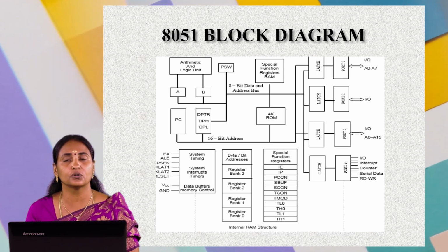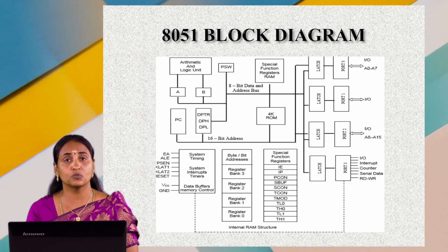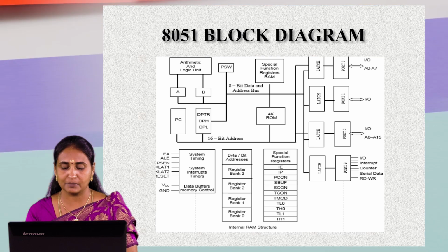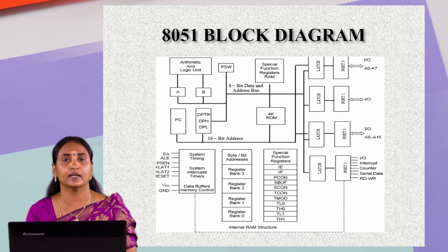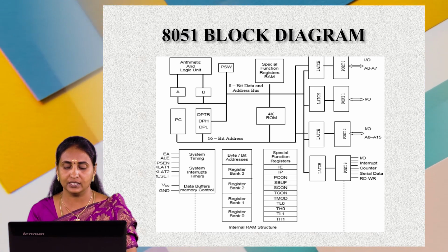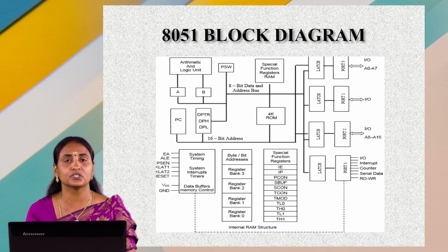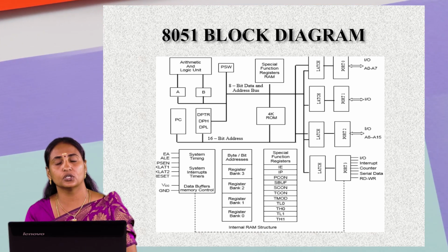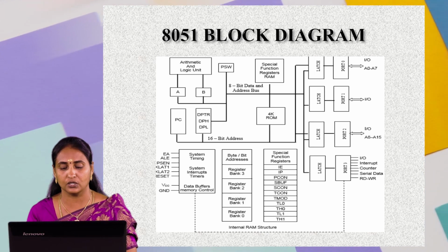This is used to control the microcontroller power modes of the device. This is not bit addressable. And the next one is SBUF. SBUF means serial data buffer. It is used for transmitting and receiving the data serially. This is only used in serial communication. Without SBUF, we can't transmit and receive the data between the microcontroller and an external device.